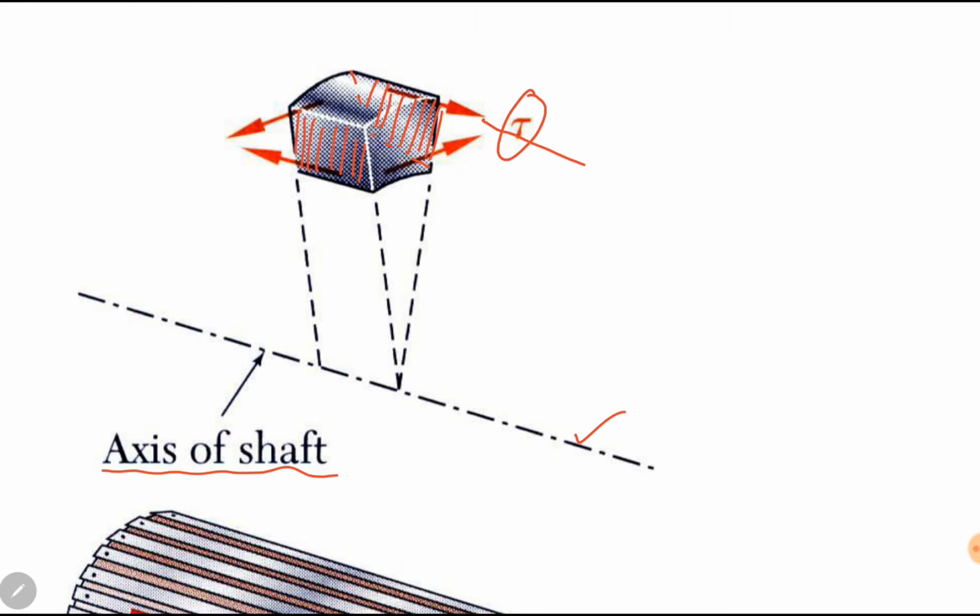This shear stress will produce a clockwise rotation if we look at this element from the top. So this will balance out the previously known counterclockwise rotation. So it has been established that the surfaces of the element of the shaft which are parallel and perpendicular to the axis of the shaft are under shear stress or shear loading.